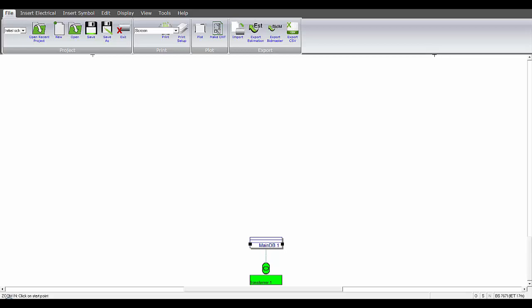What we're going to look at in this video is how you can add boards in various ways. There are several ways you can add a board to a layout. You can add them earlier on in the design process by just adding a board and putting a general load, either single or three-phase, putting the details in, adding the submain cable, or you can place the board on the layout, go into the board and put all the final circuits in.